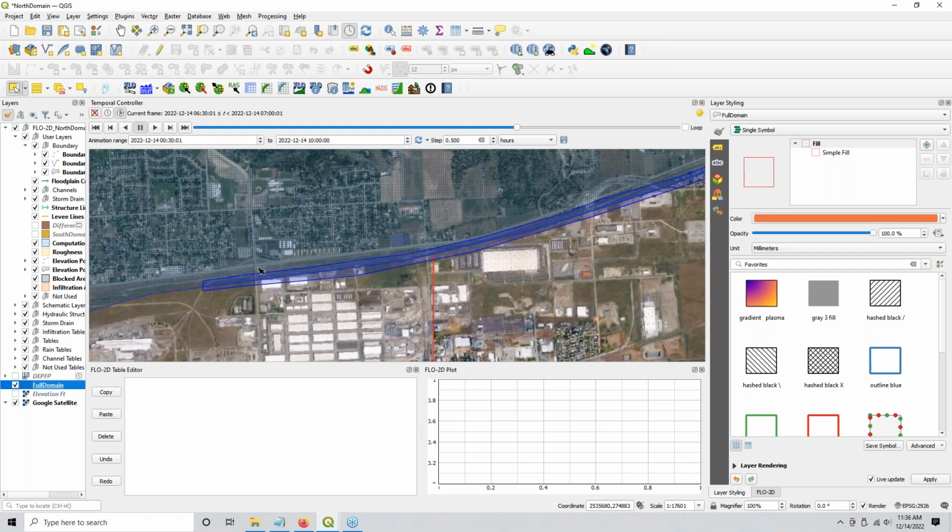How do you assess the slope and the length where you're cutting this off? You're changing the length of that pipe as it moves across that boundary. So you might have to artificially adjust the length and the slope of the pipe right here so that the water keeps continuing downstream, and maybe artificially adjust the length of the pipe on the downstream model as well.